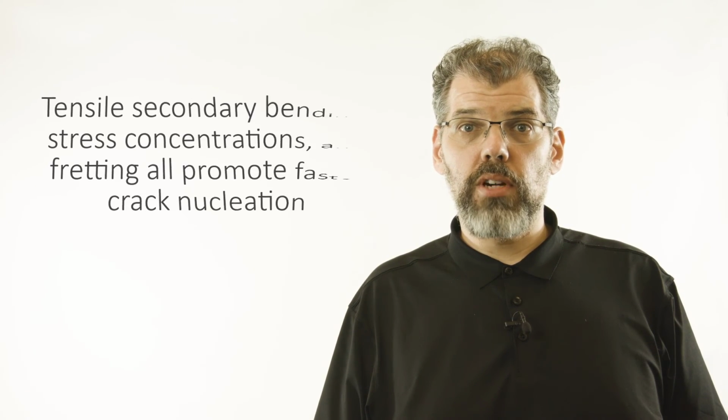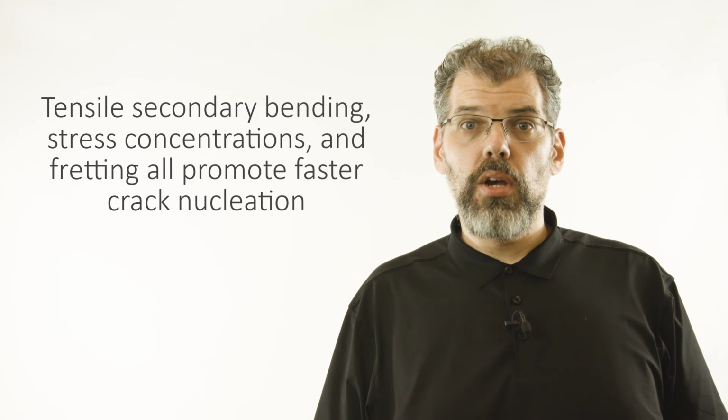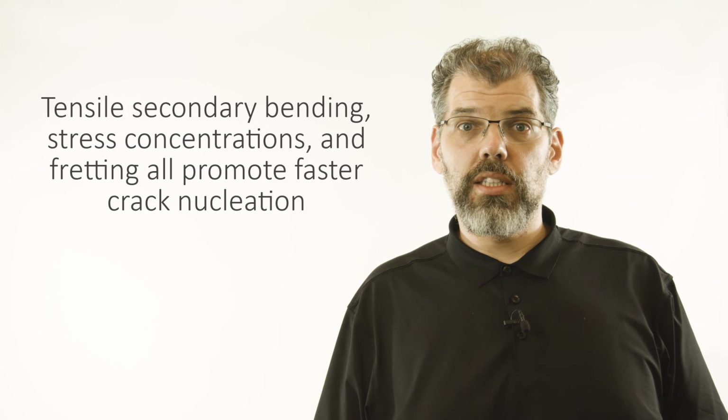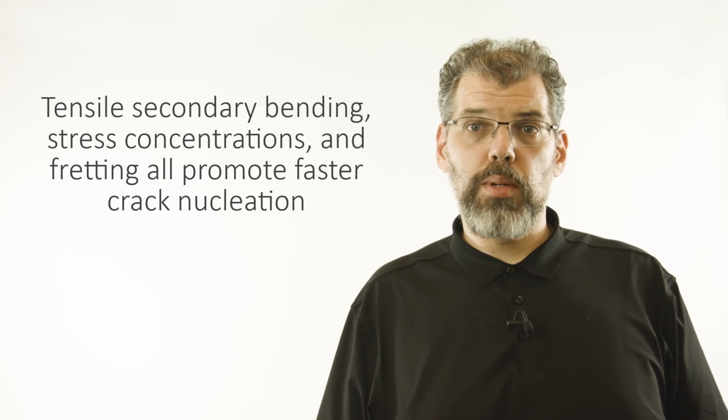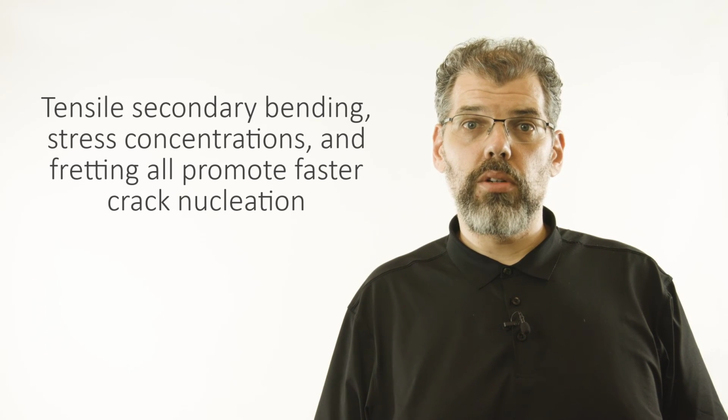Secondary bending makes this location even more critical. The eccentricity in load path within an overlap joint results in bending that produces compressive stresses on the free surfaces of the joint and tensile stresses at the mating surfaces of the joint. The superposition of tensile bending stresses at the mating surfaces of the joint with the other stress concentration and the influence of fretting damage can accelerate crack nucleation. For this reason, special attention must be paid to these risks in a fatigue-critical joint design.